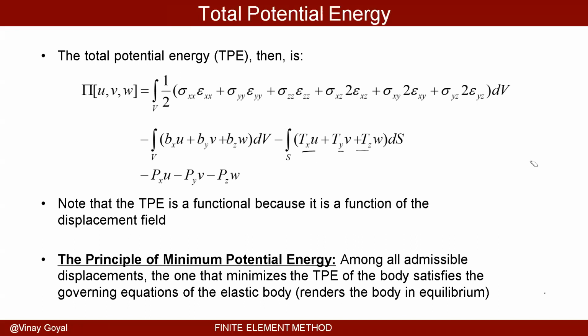As a consequence, there needs to be a volume integral. The tractions, such as lift and drag on an aircraft wing, act on the surface of the material that encloses that body of volume V. As a consequence, that traction multiplied by the corresponding deflections becomes extremely important to also consider in your assessments.